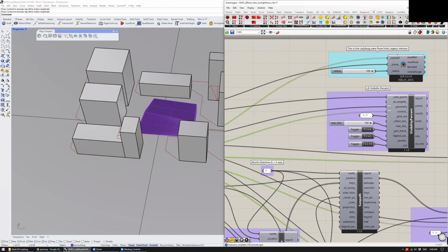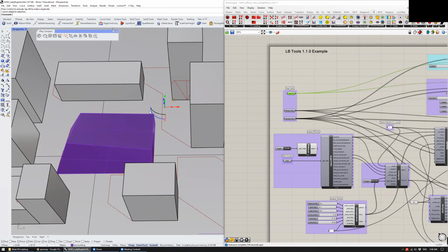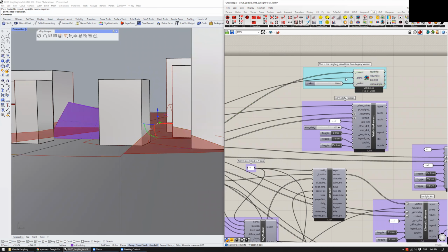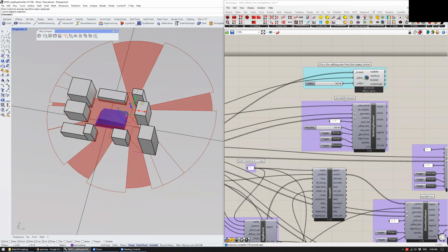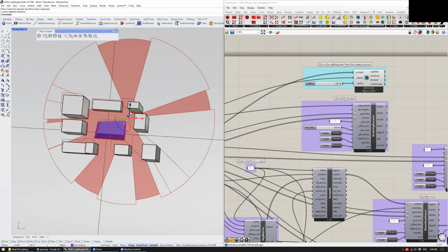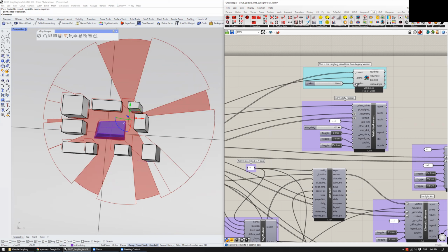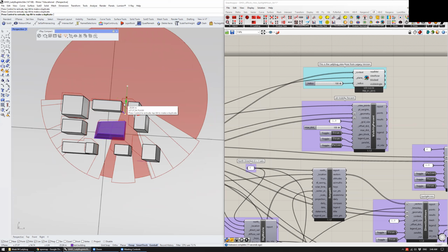Context geometry, that's it. The plane, this is the test plane, and basically I link this to that one viewpoint that I put in. Right now it's this point, and let me turn this on so you can see what it's doing. There's a radius, based on whatever units you're working in. It does an occlusion test based on your surrounding geometry. The radius controls how far it goes, so it's a view analysis. If I move the point around, it will update based on what it's seeing.